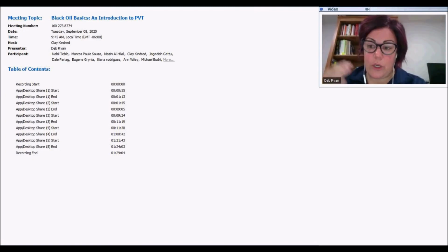If you're forecasting and you don't have production history, this is one of the reasons we use reservoir simulation, so that it will calculate how those changes with reservoir pressure will go with time. That's also really important if you've got some uncertainty about the initial GOR or other correlations: running sensitivities and tests on how that's going to vary with time. You don't necessarily have to do a huge full reservoir simulation if you're early on. There are other 2D, more tank-style ones that will help estimate some of that, or, depending on how complex it is, big full-field reservoir simulations. I don't know if that person already has production data or is trying to forecast, so it depends on where they are in their reservoir life.